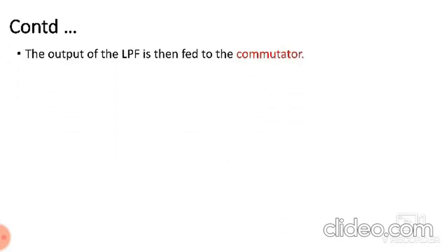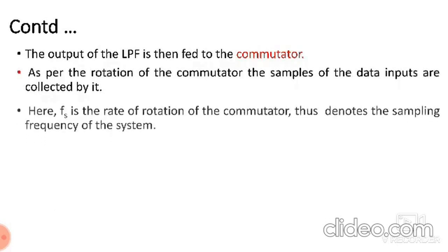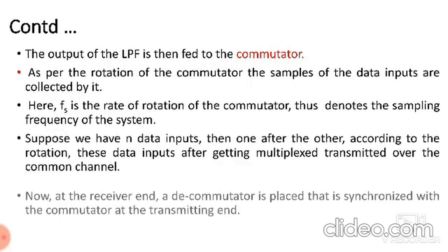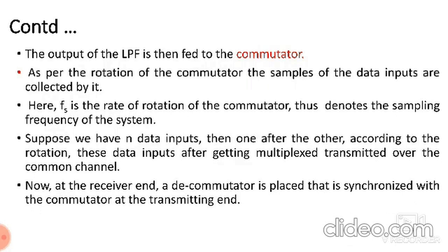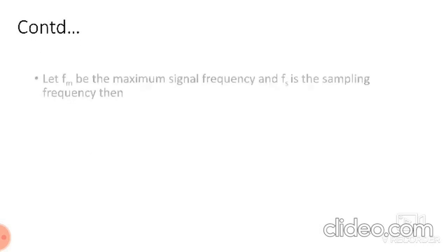The basic concept of the multiplexer is combining n number of signals by using the switch which is called the commutator. This commutator rotates and chooses the signal selected by the various time slots. The time slots are related to the switch selection, so according to the commutator's rotation, these time slots will be chosen.